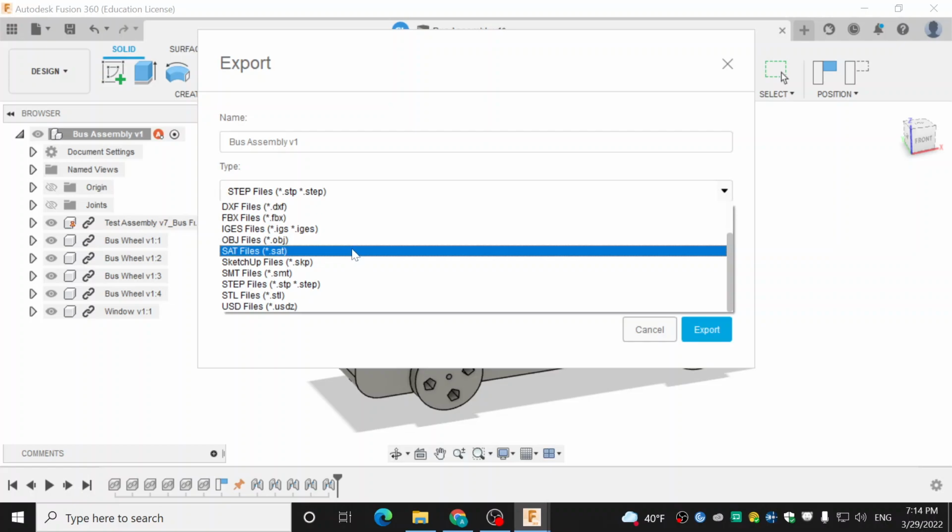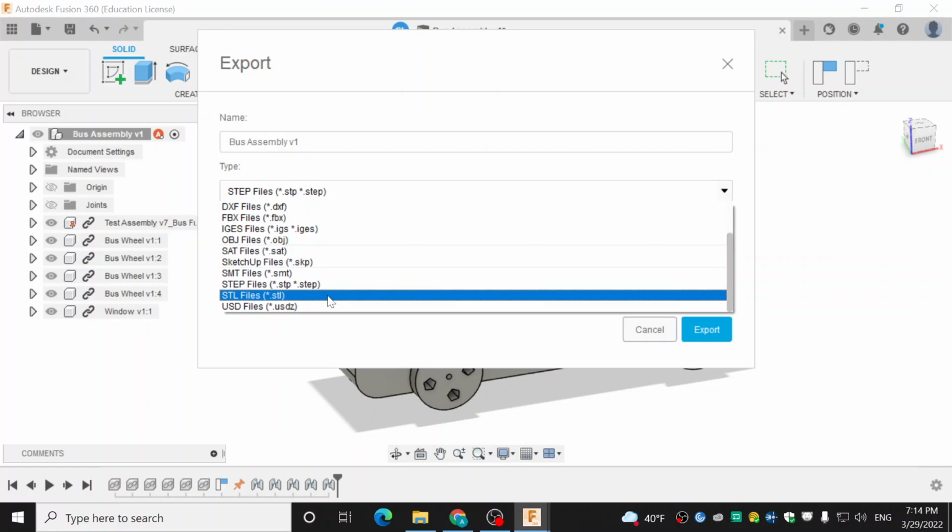it kind of gets a little glitchy when you put it in slicing programs. Because when you export it as an STL, you have to open it in a 3D print slicing program, and then that slicing program has to convert it. So sometimes it can get a little bit finicky there. You'll keep the joints though, right? Well, no. Once you export it as an STL, it's literally just a mesh of the entire thing. So you'd have to design it so that the parts mesh around each other so that when it prints, you can't pull them apart without breaking them.